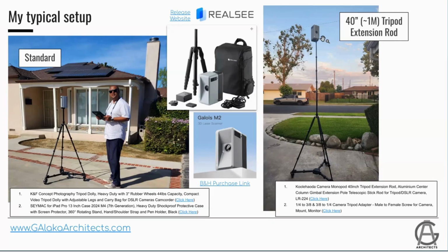Also, one thing to mention is when I do my scans, I don't necessarily do the ultra high resolution one. In my opinion, I'd rather do additional scans than make fewer, longer scans, if that makes any sense. So sometimes it's actually okay to do a scan in one spot and then lift the tripod higher, do another scan, move it a little bit left, move it a little bit right. It's better to get a lot of scans because that gives you a lot more point cloud data down the line.